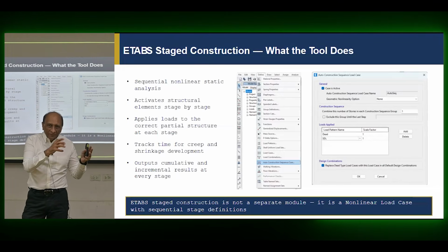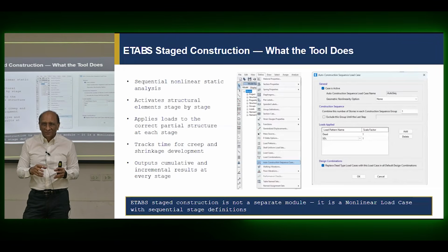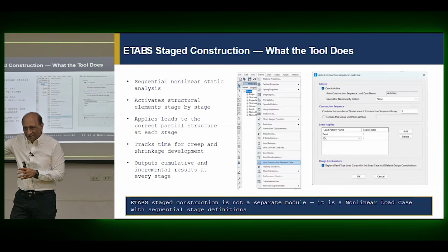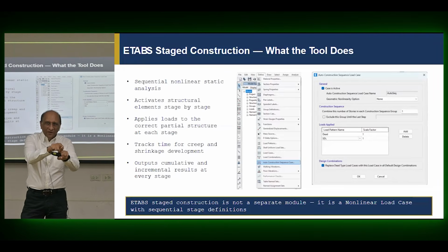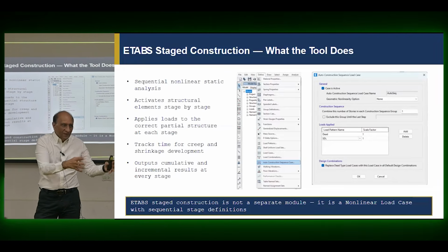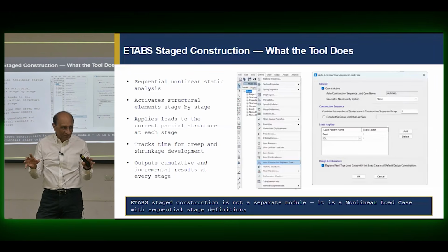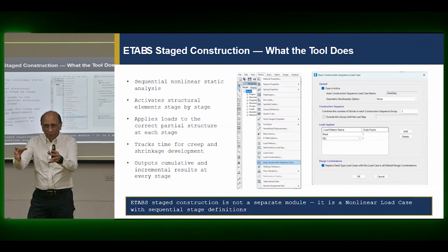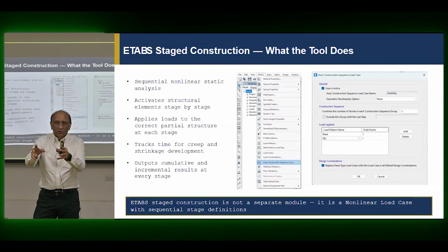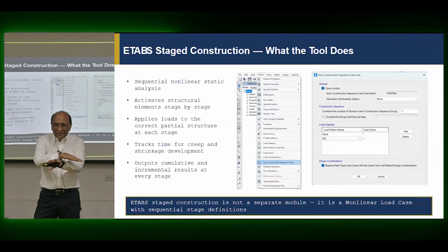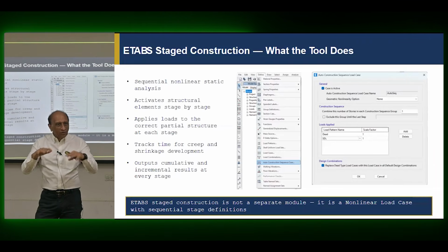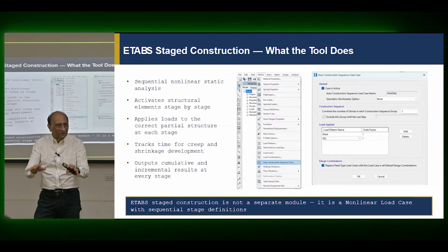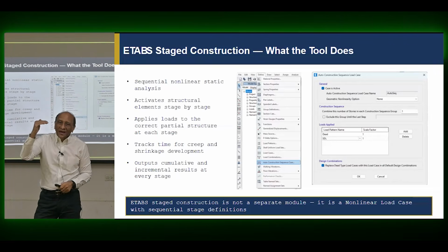Then step number 2, add load, applied load. Then you can say applied load to that group, this load case. So you have a load case, load pattern. Then you say this group, apply this load now. So you can build the geometry and you can apply the load independently of each other. Then you say now, step 2, add this group to this structure, apply that load to this structure. So the program will analyze the first group, get the results, lock them in, construct the second group, apply the next forces to the whole structure, lock that in. So you just keep on adding construction stages.